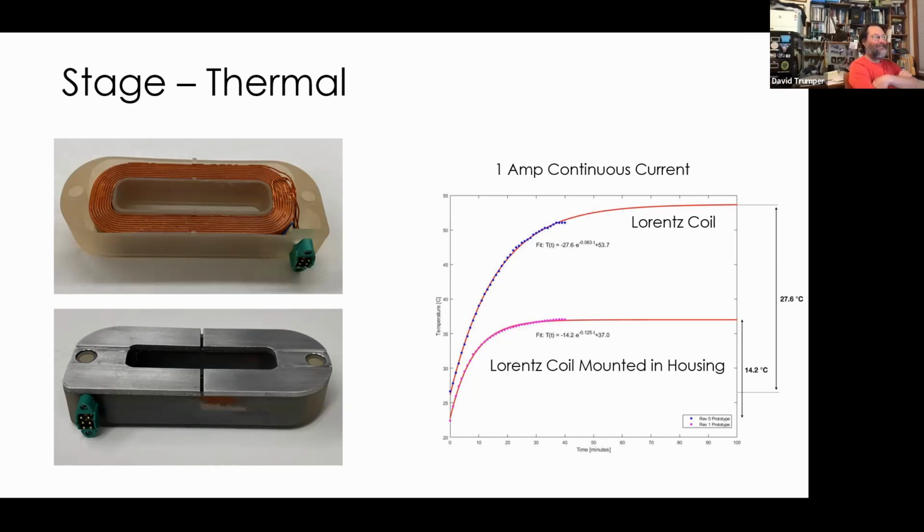So here's the thermal considerations. We thought about doing gravity offset, so having a permanent magnet configuration which offloads the main weight of the stage, and then just using the controllers to operate around that operating point. In a production-level machine, they would definitely use gravity offset because we're trying to be efficient.